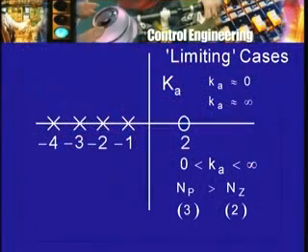Usual case is this: the number of poles is greater than the number of zeros. For our motor problem, that is exactly what is happening. The number of poles is greater than the number of zeros, because you remember the forward path transfer function G had a quadratic in the denominator, therefore only 2 poles. The feedback transfer function was only KTG, so no pole nor zero, it was just a coefficient. So the loop transfer function GH, or the loop gain GH, had only 2 poles and no zeros. So np was 2 and nz is actually 0. So certainly np is greater than nz. If this is the case, if the number of poles is greater than the number of zeros, then one of the rules of Evans says that when the gain is very small, the roots will be very close to the poles.